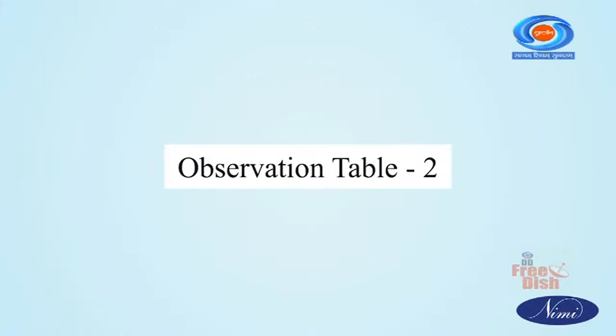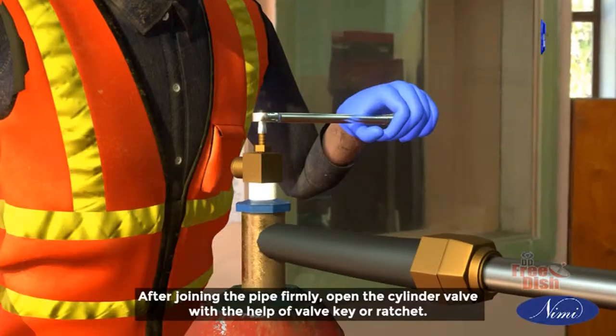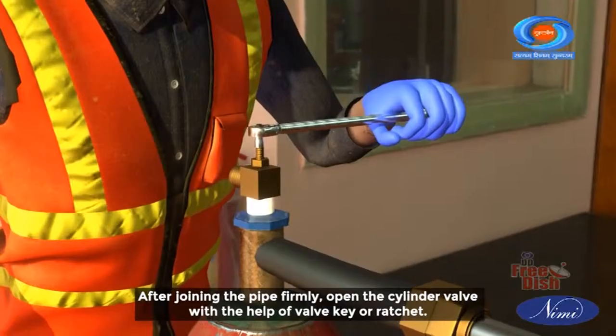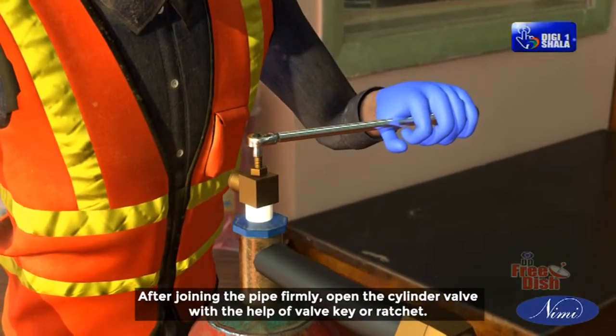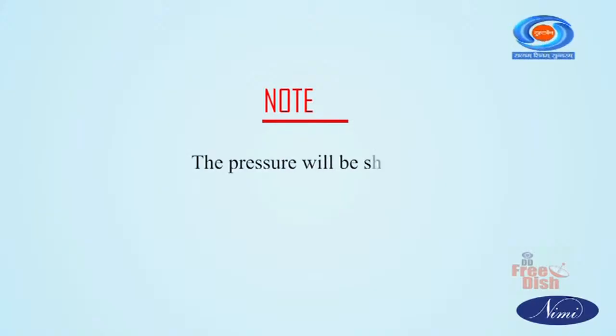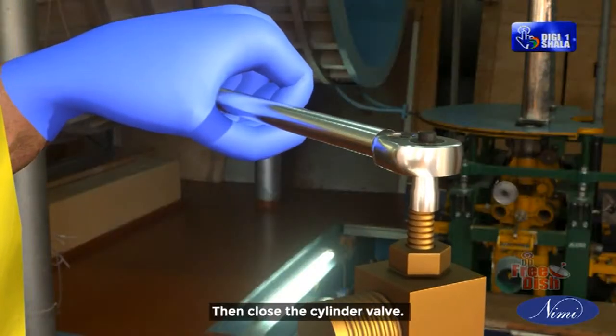Observation Table 2. After joining the pipe firmly, open the cylinder valve with the help of a valve key or ratchet. Note: the pressure will be shown in the pressure gauge. Then close the cylinder valve.